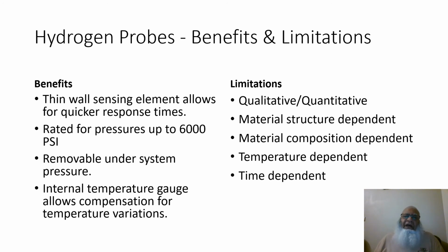This technique does not give you the direct corrosion rate. It gives you the relative change of the hydrogen pressure, and from the hydrogen pressure you can easily calculate how much corrosion there has been of the carbon steel or any representative metal which is corroding, with the active hydrogen formation during the corrosion.